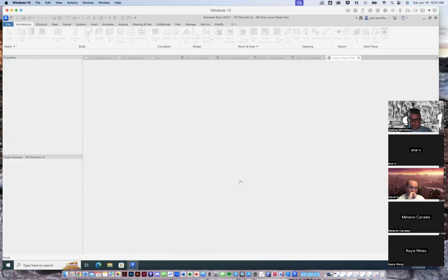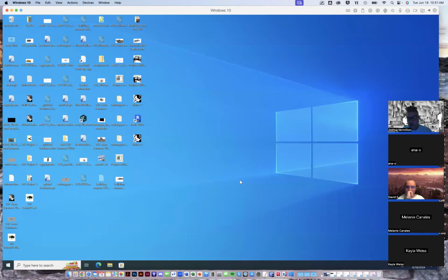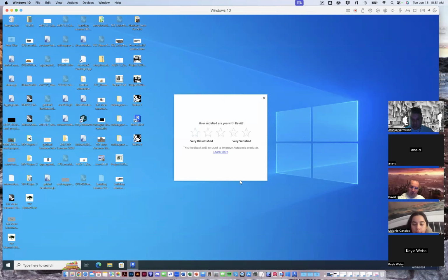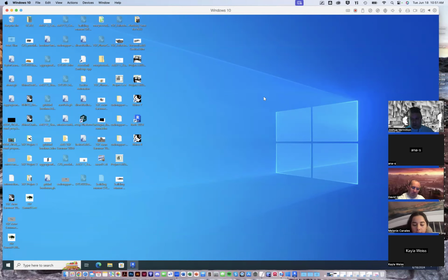All right. So that's a very, very quick primer and some of the very first steps that I find are really helpful in setting up a project in Revit. Again, I think making sure you have your units set correctly, and importing anything that you need in from SketchUp or Rhino, you can do that. You can bring in native Rhino files, native SketchUp files right in. And establishing a grid, I think, is really important, right? If you can, otherwise you're just drawing random things, right? So that grid becomes really handy. And this assignment's set up to use that grid.